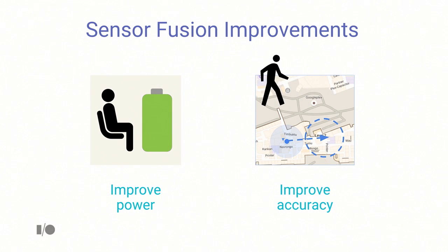We've added significant use of the inertial sensors, accelerometer, gyroscope, and magnetometer. These sensors don't tell us where the user is directly, but they describe how the user moves, so we can use them in conjunction with GPS and Wi-Fi to improve location. One example of how the FLP uses the accelerometer is by activating it when the device is stationary in order to save power. Rather than performing costly Wi-Fi scans over and over again, we rely on the low-power accelerometer to tell us when the device moves, at which point we resume Wi-Fi scanning.